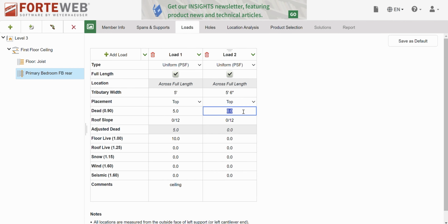All right, let's keep going. Let's go ahead and do this front beam here and see what it's holding up. What is it holding up? Well, the ceiling's running left to right, so it's not that. And the roof's braced down to everything else, so it's not that. So why is it here? Well, it's here because its job is to hold up this little piece of gable that I was showing you here. Remember this? This piece of gable has to be held up by something. So that's what this beam is going to hold up.